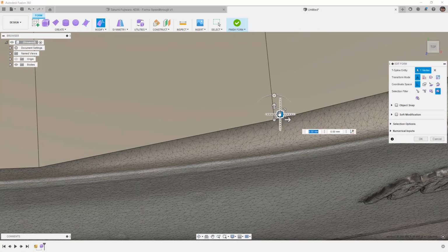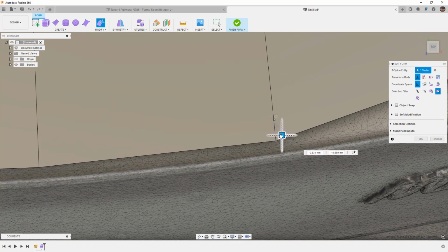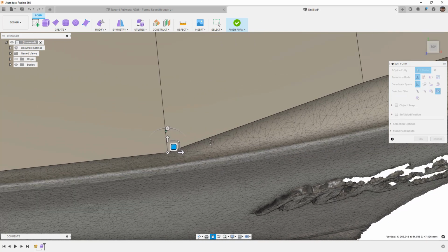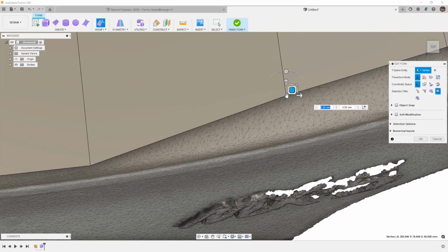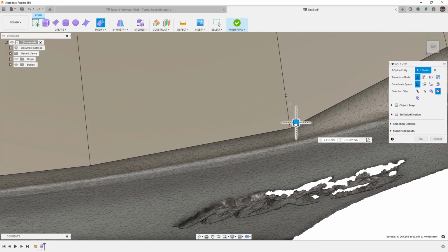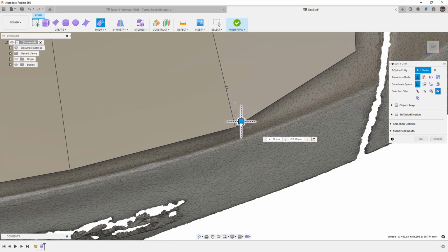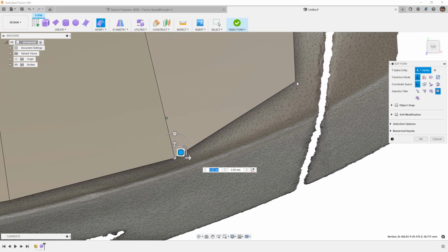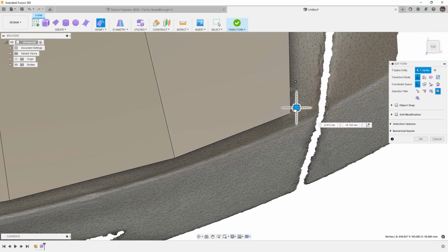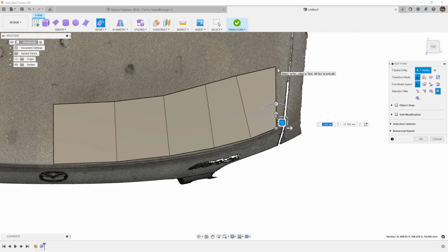The closer we get here, the more dangerous this becomes actually, because as we begin to automatically project down to the mesh, it could try to roll over the back edge. So you do have to be careful. Don't stick it way out here. In our case, I'm just getting relatively close, and I'm going to add an additional edge here to get the resolution a bit closer. Also think long and hard about how far out you want to go with this.